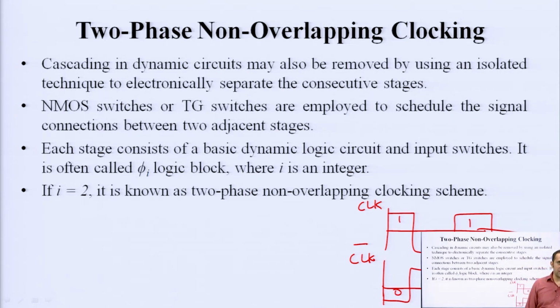In this kind of a scenario, if you use a circuit which uses both complementary and non-complementary clock, you would assume or expect one to be 1 and another to be 0. So, if you have a clock signal, pass it through an inverter and get clock complementary signal, right. But every inverter is going to have some kind of a delay. So, at some point of time you might see that both the complementary signals are either 1 or 0, okay, which is not allowed. This is known as clock skew, and in some cases when the output does not follow the changes in clock signal, that is also referred as clock skew.